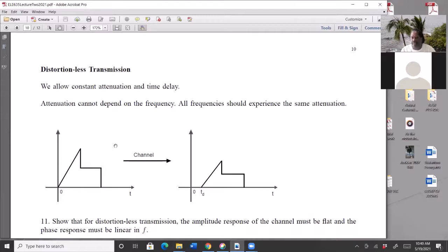Just like the inverse square law just attenuates the amplitude. So this is very important. Whenever the shape is preserved but attenuated vertically, digital communication systems work fine. But if this length is 7 microseconds and that becomes 8 or 9 microseconds, we are screwed.